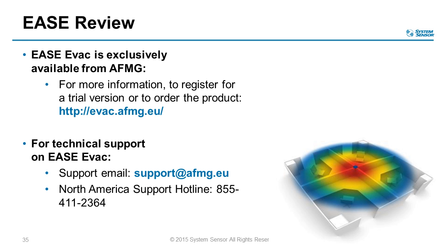We do classes on it. It does use the same speaker data, however, as EASE Evac. So any of the devices that are in EASE Evac and any of the devices that are in EASE can generally be used in either program. EASE also calculates STI. It does not have the nice automatic layout of ceiling devices. But because we can export to EASE from EASE Evac, then you can start the design in EASE Evac and then port it over to more complex room.